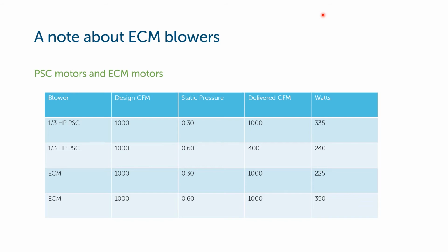And that excess heat builds up in the cabinet and gets returned by refrigerant to the compressor. Now the heat pump runs at high temperature and refrigerant pressure, returning more heat to the outdoor compressor. It runs longer and harder with reduced efficiency, both because it's trying to heat refrigerant that's already hot and because the heat isn't getting to the home to satisfy the thermostat.